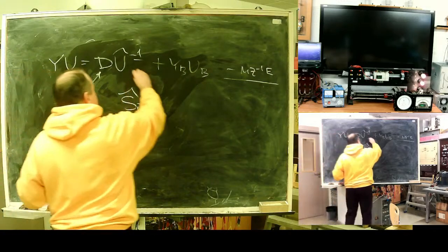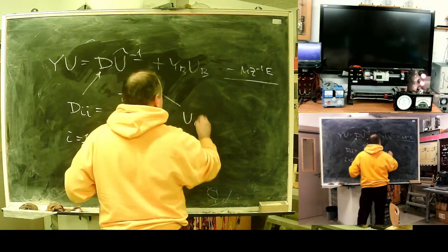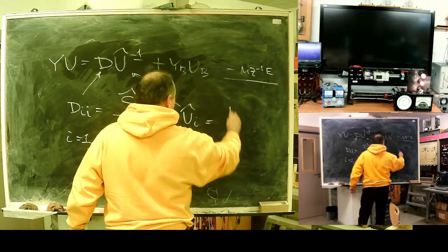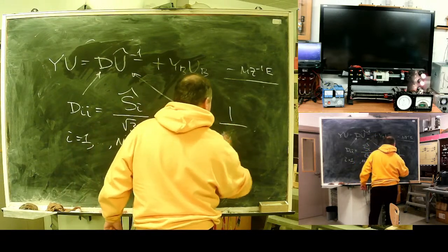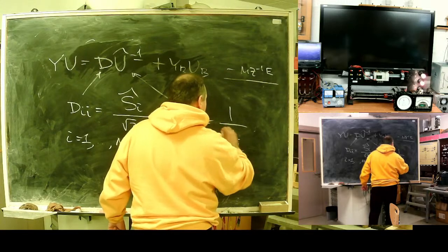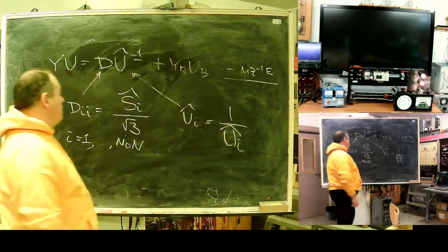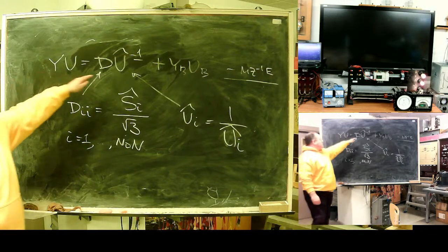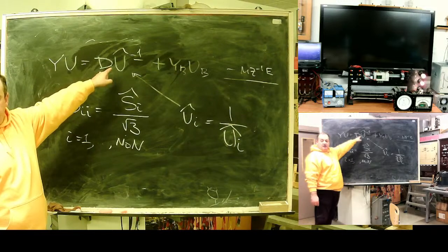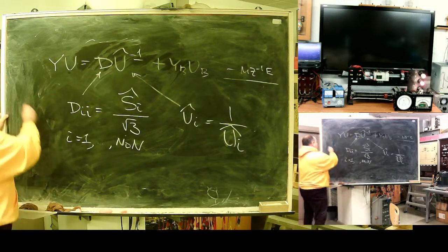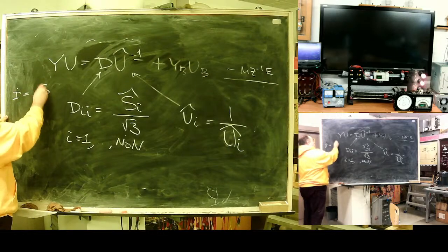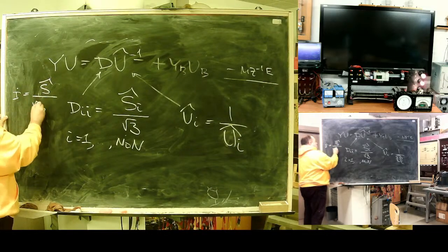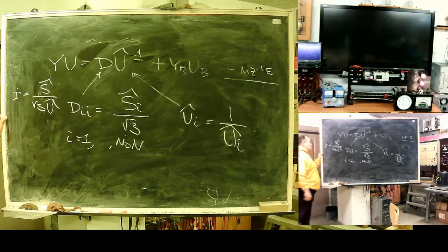And this one is 1 divided by the conjugation of the appropriate node voltage. You see, here I put a current, like in my formula. Current is the conjugated power divided by square root of 3 times conjugated voltage. Using this, I got nodal currents.